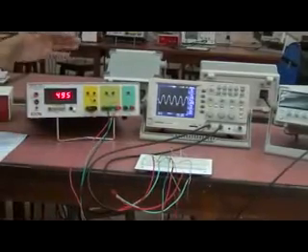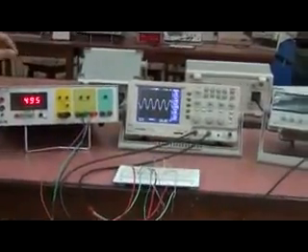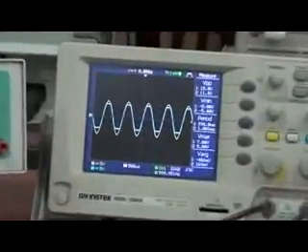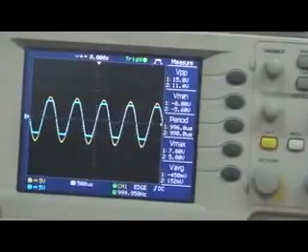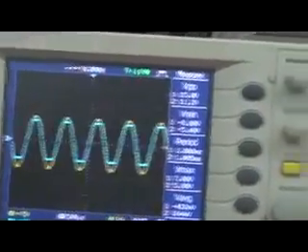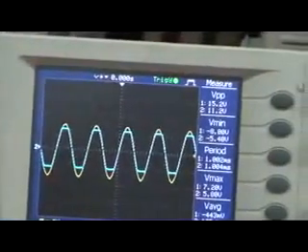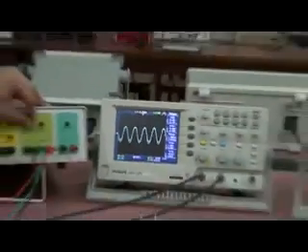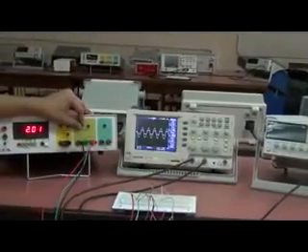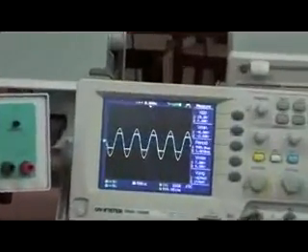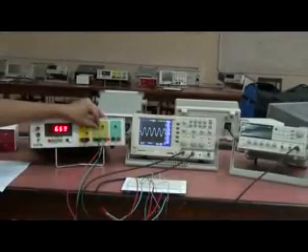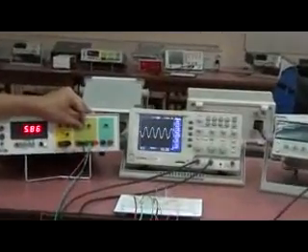So we can see from the DSO waveform that both the positive and the negative cycle are being clipped by this circuit. So this circuit is called a clipper. We can vary again the clipping through varying the power supply given to the circuit, that is VB and VB dash. We can have different clipping values by just changing the power supply.